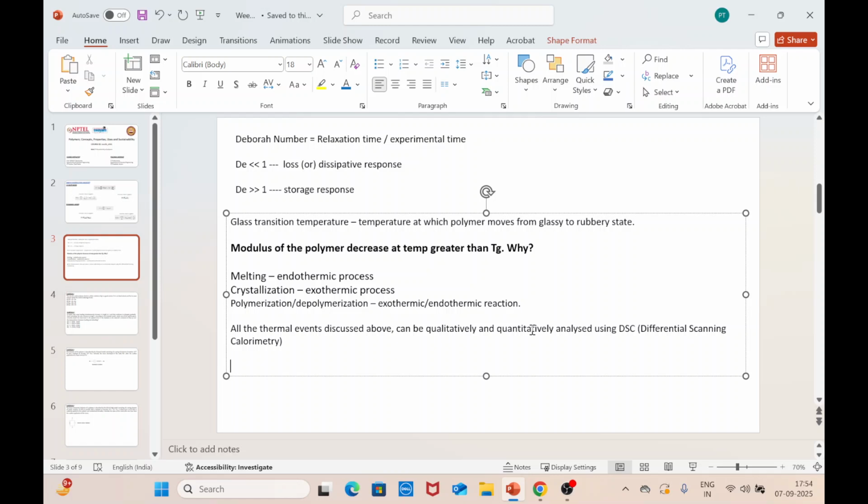So this Tg is going to be affected depending upon the way we scan. So the Tg actually varies depending upon the scan rate. Here the scan rate is nothing but the rate at which you vary the temperature. In fact, based on the differences that are exhibited, we can analyze the type of changes that happen in case of the polymer.